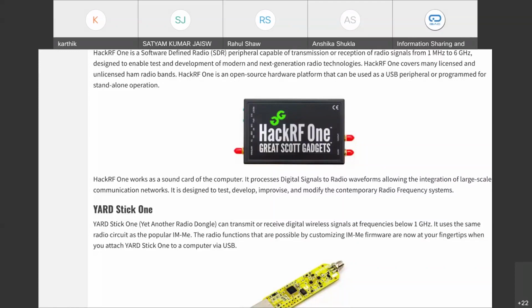So what I'm trying to say here is, these kinds of SDRs, you can configure with just a click of a button. At the click of a button, a Wi-Fi router immediately becomes a BTS station. And then at the click of a button, you can configure it to work as a walkie-talkie. If two persons have BladeRFs, they can transmit signals over radio and convert that into audio. You can connect the SDR to your laptop and use your laptop's microphone and speaker to make it a walkie-talkie.